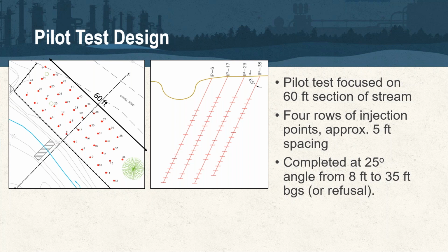Now, the injection system that we use for our bedrock sites has pretty high flow capacity, up to 300 gallons a minute. And so we have used that selectively on some overburden sites where we are working deep and we can really push the radius of influence. So maybe, in that extreme case, if you're bringing that unit out, maybe you're working on a 15-foot spacing. But in general, we're on that 5 to 10 foot range.